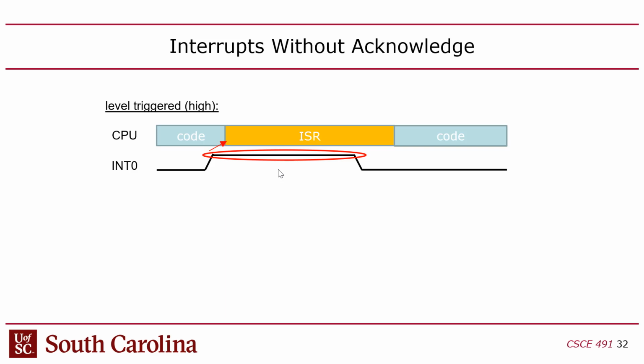Okay, and then we talked about interrupts, and this is more of a conceptual thing. I don't think we're going to actually use interrupts in the labs, but the idea is that an interrupt is a way for a device to get the CPU's attention, and then the CPU, in response to that interrupt, will service it using an interrupt service routine that could be in the operating system, or if you're doing bare metal programming, it's in the hardware abstraction layer, right? And there are different ways to set up interrupts.